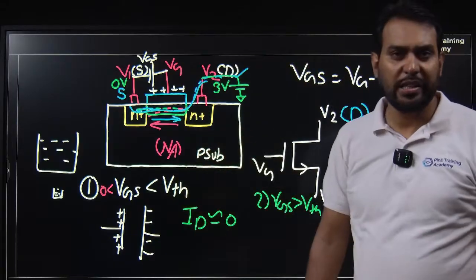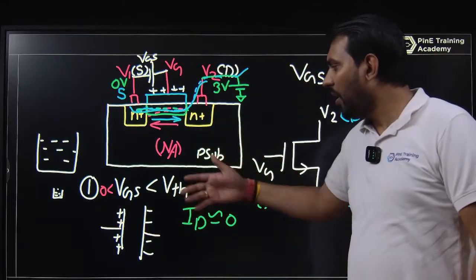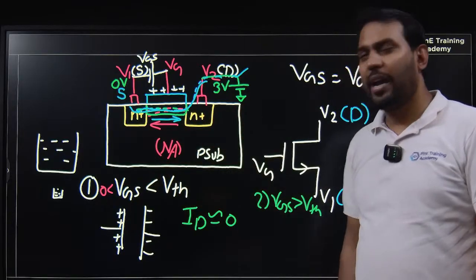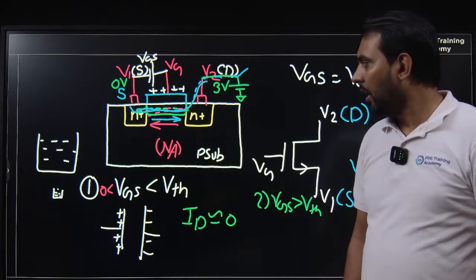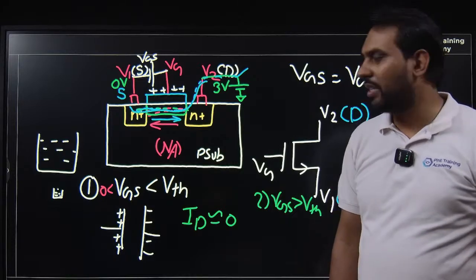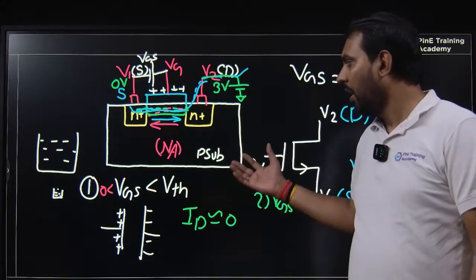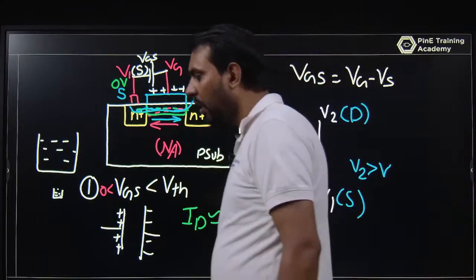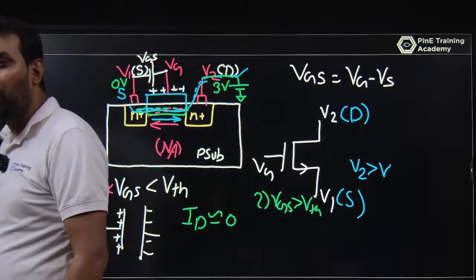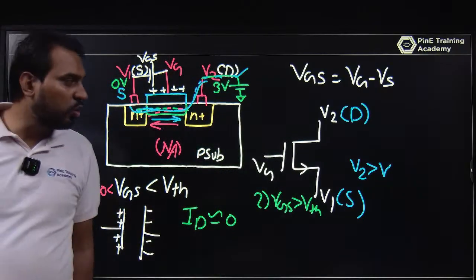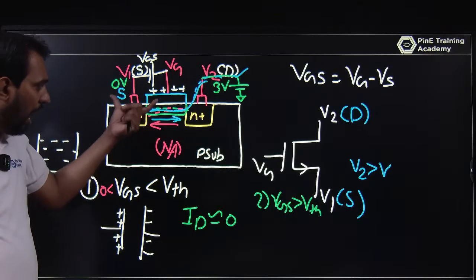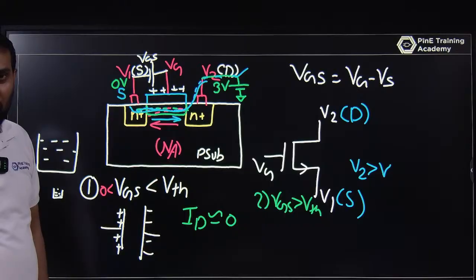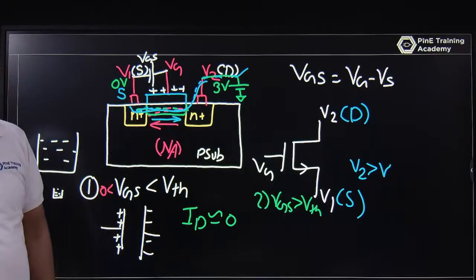Okay, we will explain in our next class, and tomorrow we will discuss ID versus the input characteristic and output characteristic. I will try to cover this part as best I can, and after that we will design it in Cadence Virtuoso. There we will simulate the graph of ID versus VGS, the effect of W by L, the DC sweep, the operating point, how you can determine the voltage of the different nodes, and what the region will be on the basis of VGS.